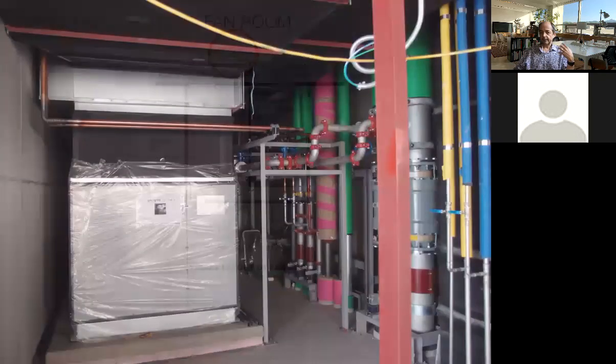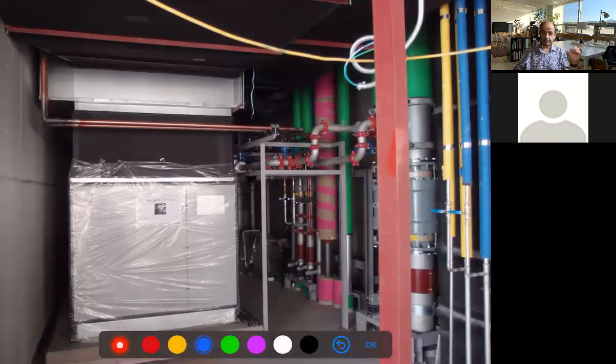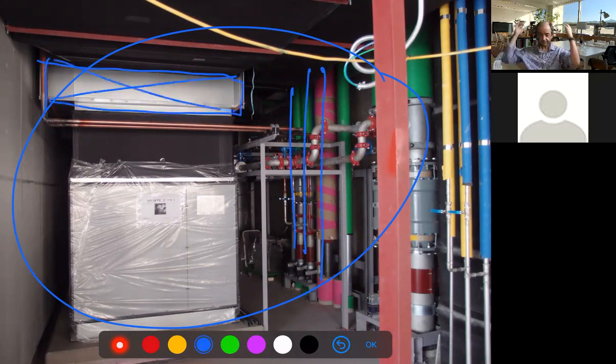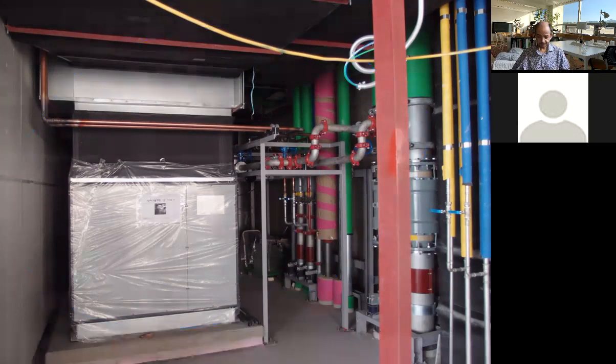This is the case of the KT building in Gwanghwamun, which we have mentioned many times. And this building has, as I remember, one fan unit per floor. And you see the size of that room. It's not small. And you see the size of those pipes with the insulation. And you see the size of the main duct going to serve just one floor. This is enormous, right? If you do not consider this from the beginning, you have a huge problem reorganizing the spaces and the shafts in your building.